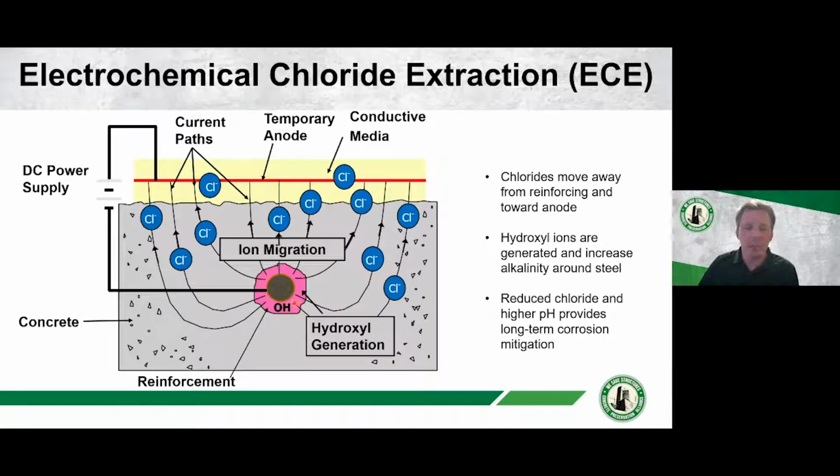I should have touched on that a bit earlier, but when you use mild steel and install it in concrete, when it's new, what's created is a hydroxyl or a passivating layer around the reinforcing steel. That protects the steel, but chlorides do a very, very good job of breaking that hydroxyl layer down.